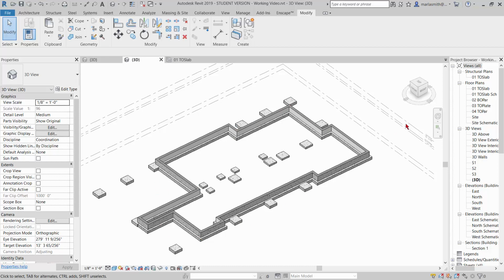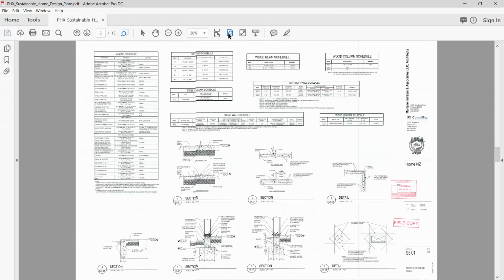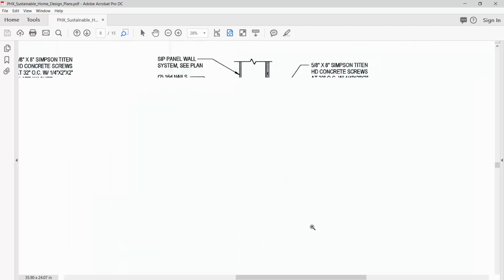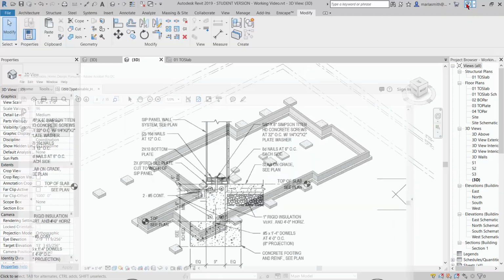These are actually open, don't have a slab on them, so it's just these two. So let's take a look real quick at the section that we've been working with. In our section detail, the floor slab has an inch of rigid insulation below it. We've got the inch of rigid insulation on our foundation wall. We went ahead and added that. So we're just going to draw this floor from the inside face of the wall, since we already have the inch of rigid insulation on that wall.